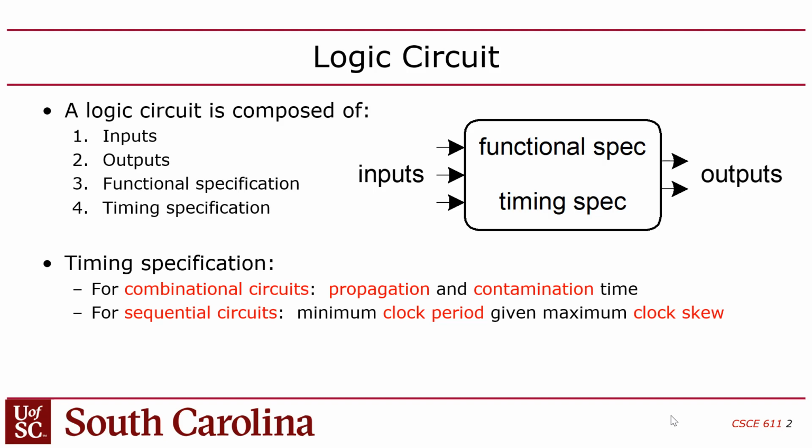But the problem with automating is you're not seeing everything that goes into that project. One of the things in that project is a pin mapping file that maps the names of your top level inputs and outputs to specific pins on the FPGA. The other part is a constraint file that says that you need to synthesize this so it runs at 50 megahertz, because we're assuming a 50 megahertz clock, which means a 20 nanosecond clock period, which means that your worst case logic delay of all the combinational circuits in all your data paths